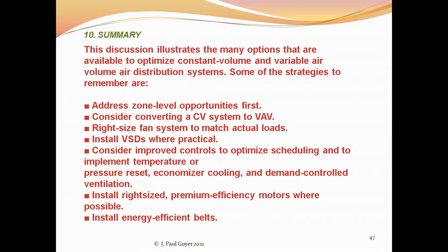Consider improved controls to optimize scheduling of turning the system on and off and that sort of thing, and to implement temperature or pressure reset.